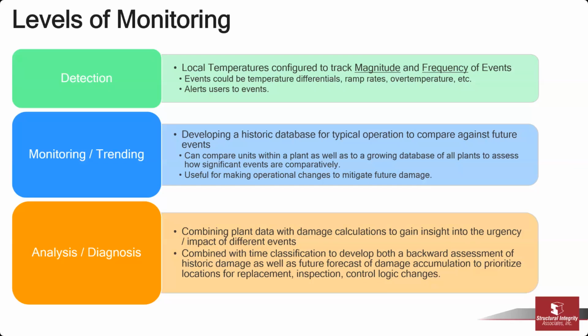So that's kind of the next step, is using the additional instrumentation that was installed to ultimately build into a damage model. And certainly there's always going to be complications with damage models, because with any analysis there's assumptions, but we're basically trying to build the best analysis we can with the information available. So I would say generally when you're doing monitoring, you're going to try and be conservative on a lot of these damage calculations up front, just because you want to be on the conservative side of things rather than have a failure.